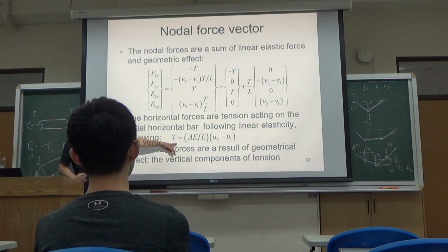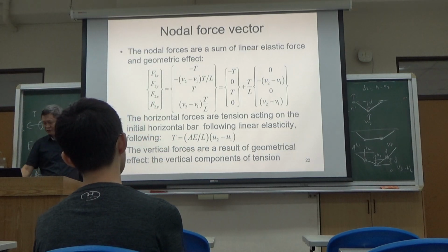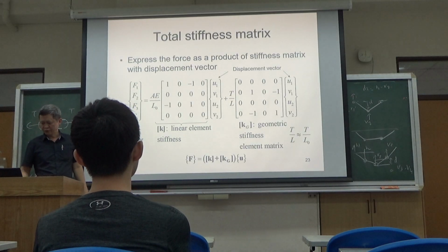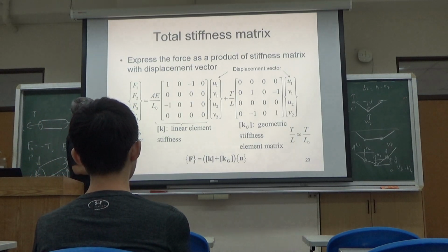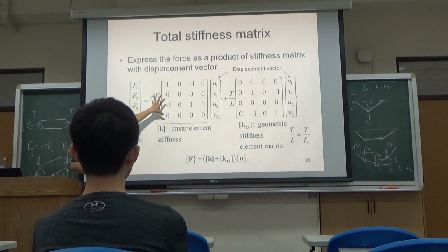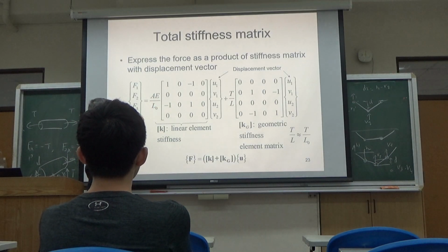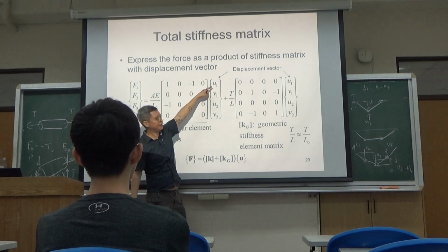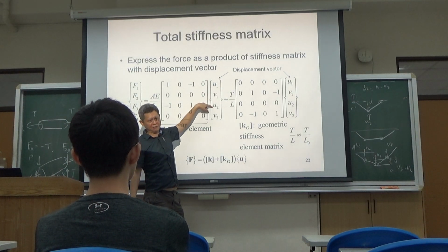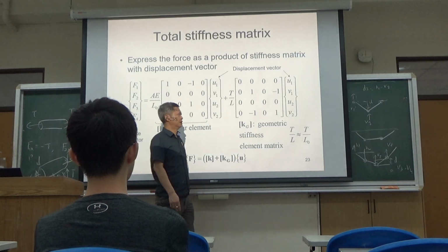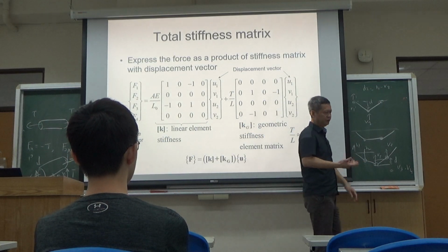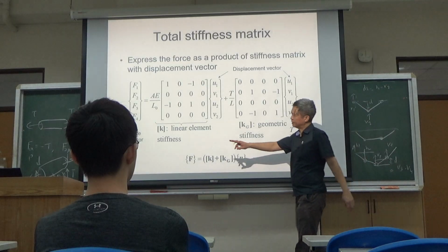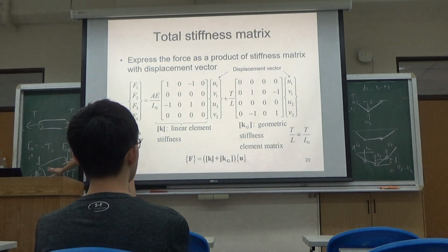So in a way, you can say, yeah, this is different from the cable tensions. So in short, what is the total stiffness then? The total stiffness comes now from two parts. One is the bar elongation. This is your linear stiffness. It only happens in the cable length direction, U1, U2. But now because of the pretension, there is a support of vertical loading.